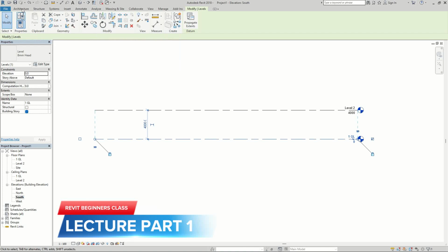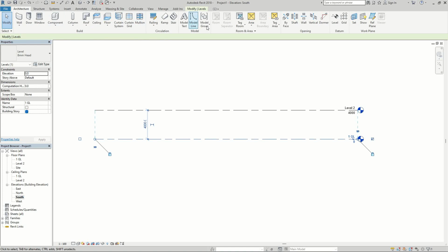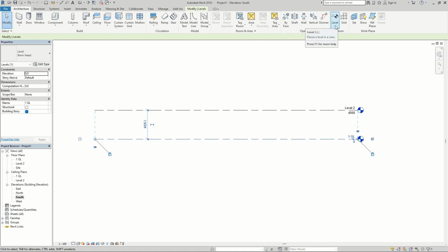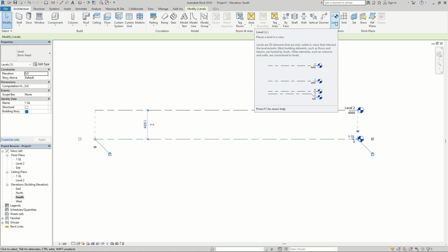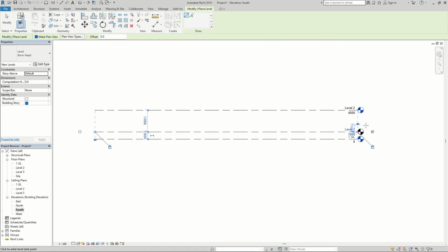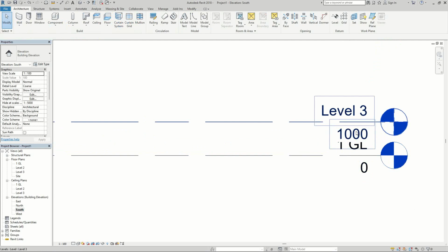Or you can go to your architectural panel space, which is the ribbon, and select the level and see the same level. You can see details of that. Okay, so I'm showing the two ways you can get that. You can click on this one and as well click a particular height and end it by clicking on the space. I want to stop this one again now. So now you can see it shows a height of 1000 millimeters.